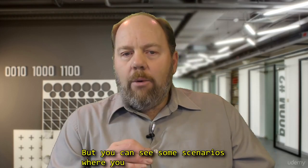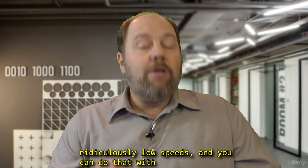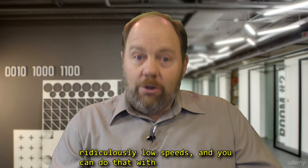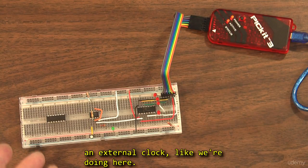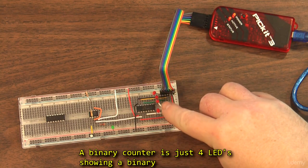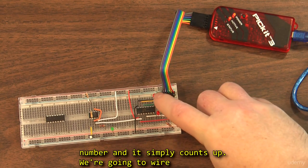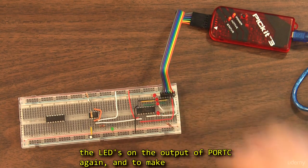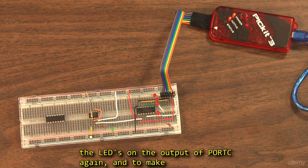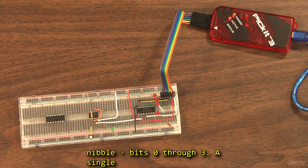They'd be flashing on and off so fast, it would just appear as though the LEDs were constantly on. But you can see some scenarios where you specifically want to run the processor at ridiculously low speeds. And you can do that with an external clock like we're doing here. So a binary counter is just 4 LEDs showing a binary number, and it simply counts up.